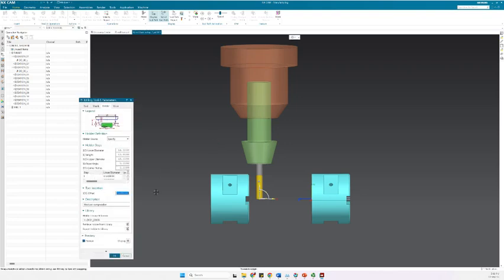And then you still have to choose the offset. So, for example, what will happen if I put offset 0? There wouldn't be any connecting point between this holder and shank. So the more this value is, the greater the amount that is going to be inserted inside the holder, and it will be clamped here. So for example, let's keep it as it is.